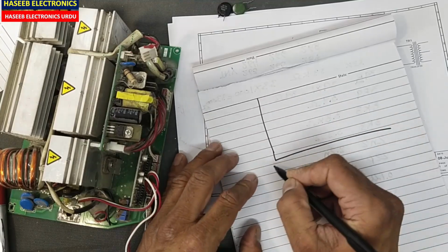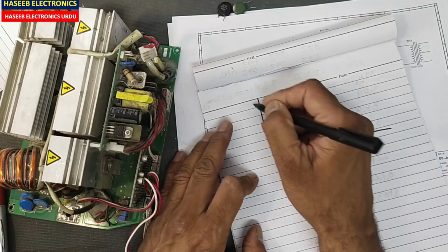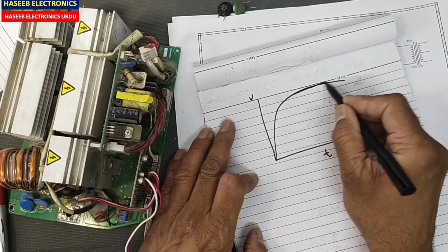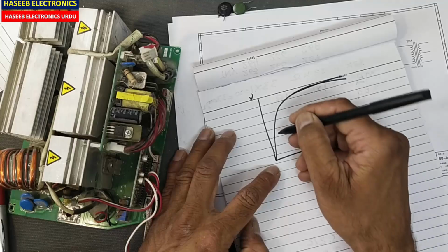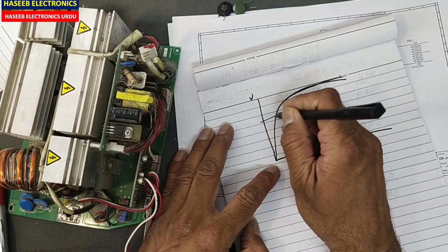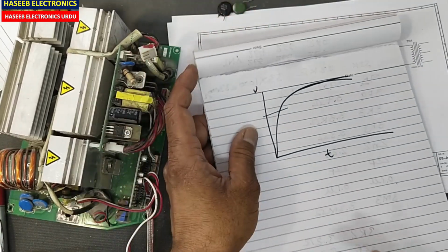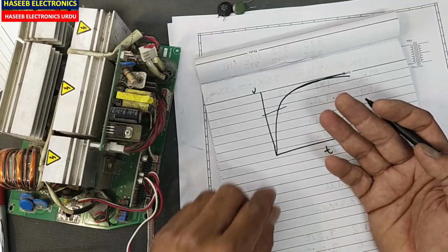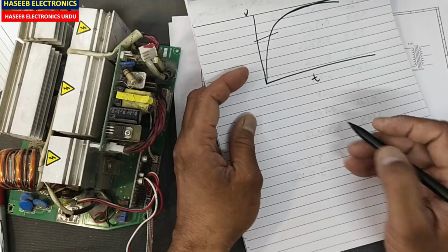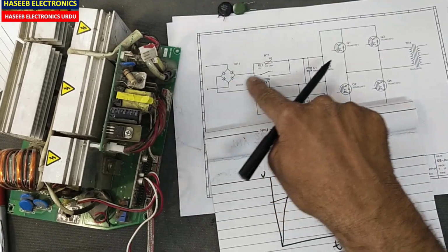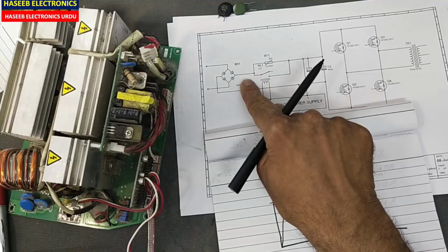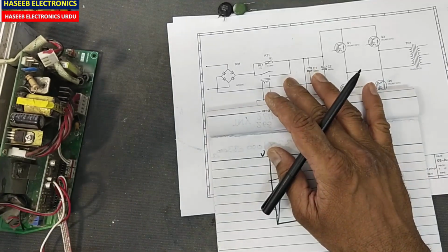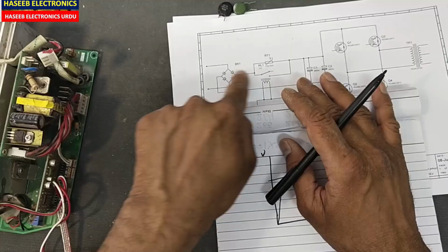Voltage against time and voltage. The capacitor charges in this way. At this stage, at its first charging time constant, 63%, at that time its internal resistance is near to 0. So at that time, if you connect directly a bridge rectifier to any charging source, it will draw maximum current that can damage the circuit, that can damage all the items on the board.